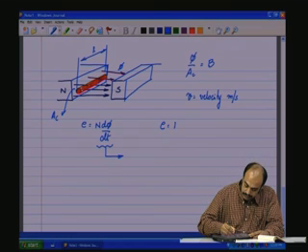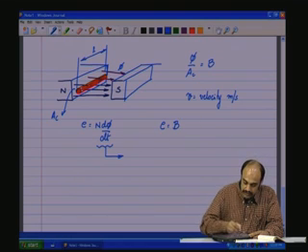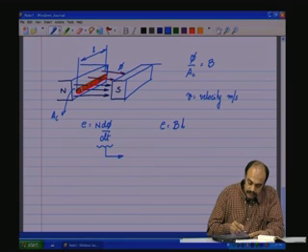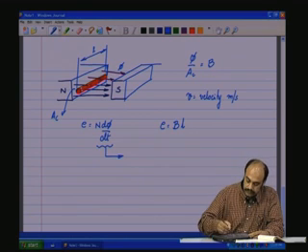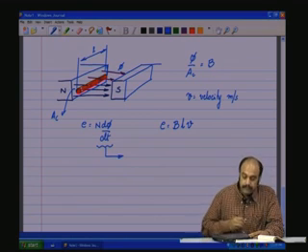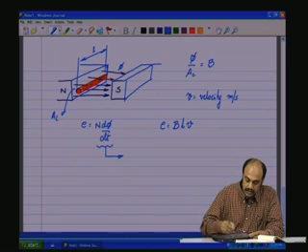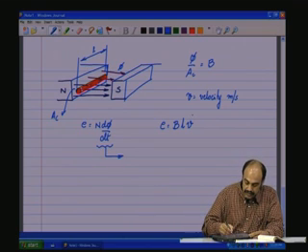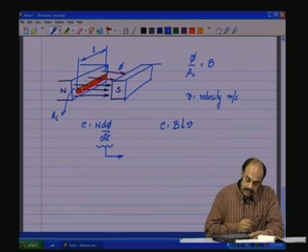given by B, the flux density, which is a constant of course in this case, because phi is a constant, AC is a constant, L is a constant again because this is the length of the conductor, and V, which is the velocity at which this conductor is moving in meters per second, and this is what is cutting the flux.